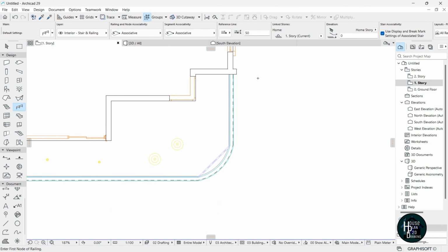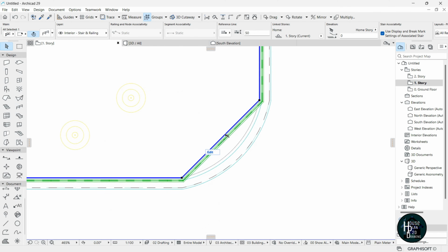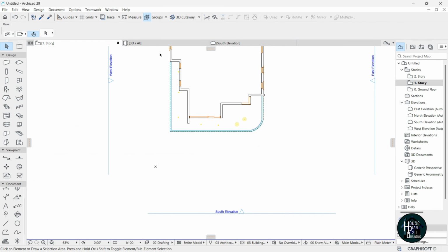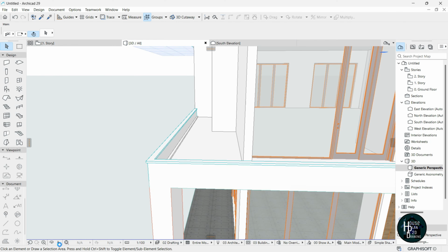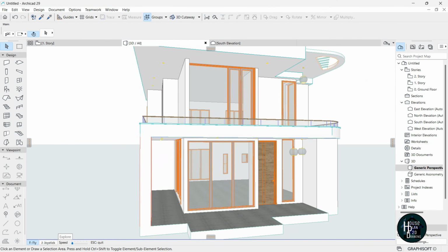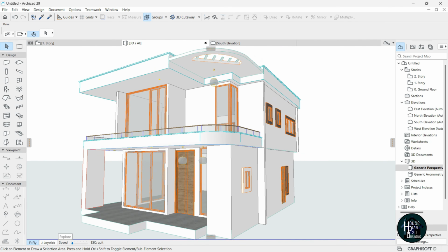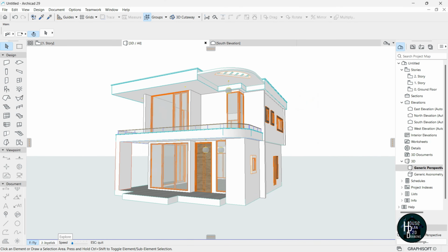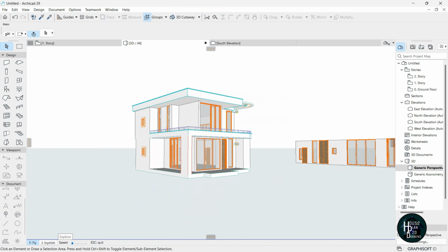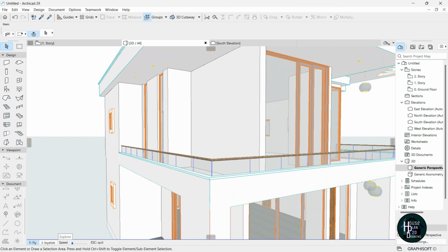Then double click this side. Now click on this edge here, look for the curve edge, and let's try and curve the edge to like this. Now go to your 3D model to check what you did, and you're going to have that design come out as perfect as this, as you can see. Okay, so this is one of the ways to make your designs look perfect.